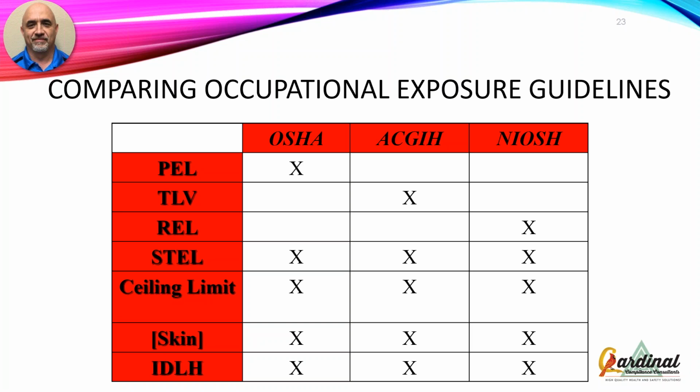So a lot of the permissible exposure limits that we see in 1910.1000 Table Z, Z as in zebra, go back to the 1968 data from the American Conference of Governmental Industrial Hygienists. A lot of them do. Now, we've had some that have changed: silica, asbestos, lead, hexavalent chromium, cadmium, but they're changing those on a contaminant by contaminant basis. That's how they're having to go through and do it. But that's why I talk to you guys about what that definition of a permissible exposure limit is.